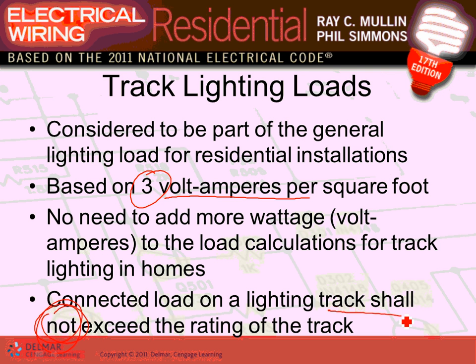You don't add extra for them. If it was a commercial building, by the way, guys, we will add. You have to add. But for track lights and so forth in dwellings, no extra volt-amps.